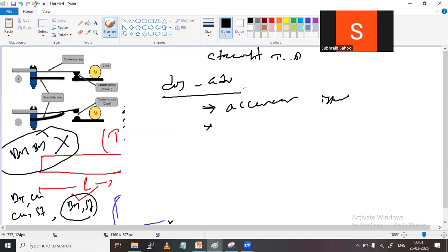direction, right direction, left direction. So every time, with respect to temperature change, the metal is going to be bent always. After a certain period of use, suppose 2 years, 3 years, then in that metal permanent deformation will form slowly. So for that reason, the result it gave in the new stage, after 2 years the same result may not be given. So we are going to find an accuracy issue in this device.